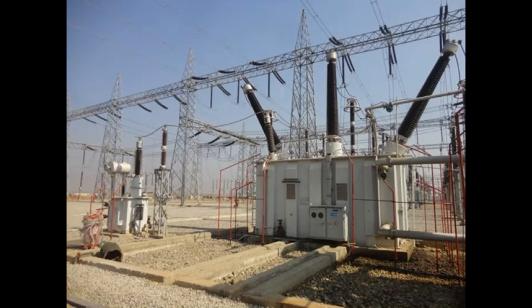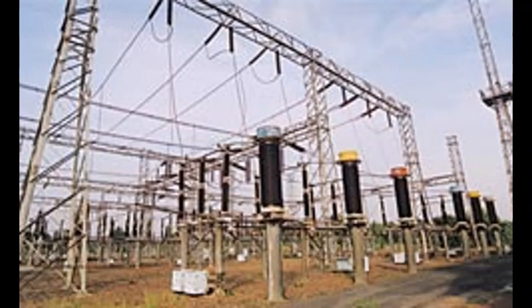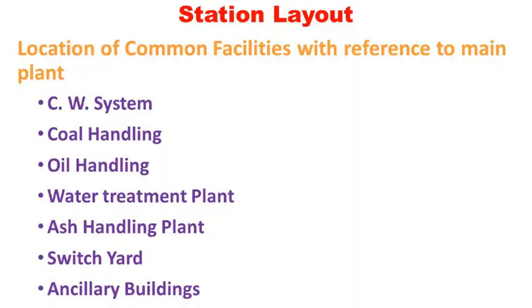In general, switchyards are placed in such a way that fire safety arrangements as well as cleanliness can be maintained, and appropriate overviewing of the performance of isolators, breakers, transformers, their maintenance and servicing can be taken care of.